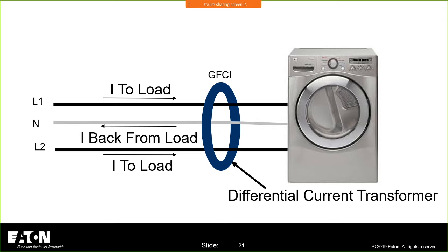So this is an example. I get this question a lot from an appliance perspective, and sometimes you may not even have that neutral. I know some spa panels and pumps, they run 2 hots out there, and that's all they got.